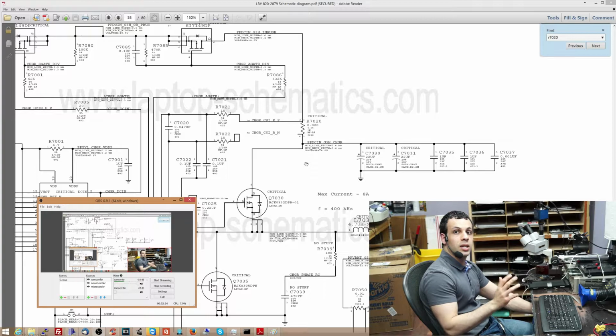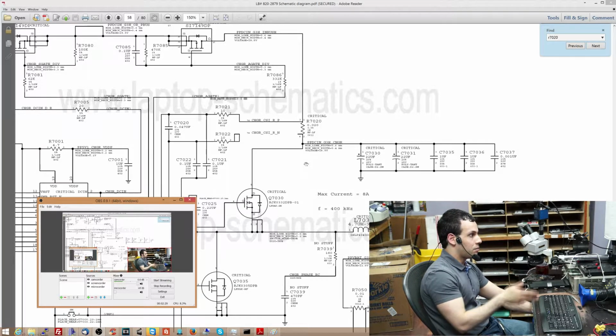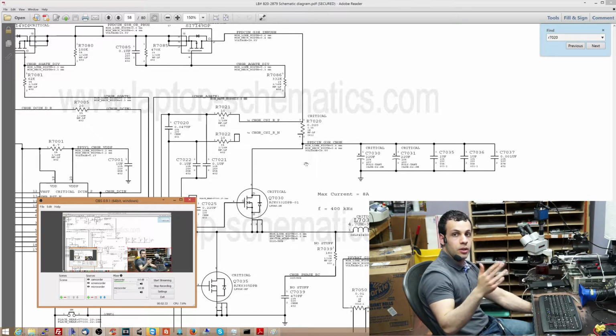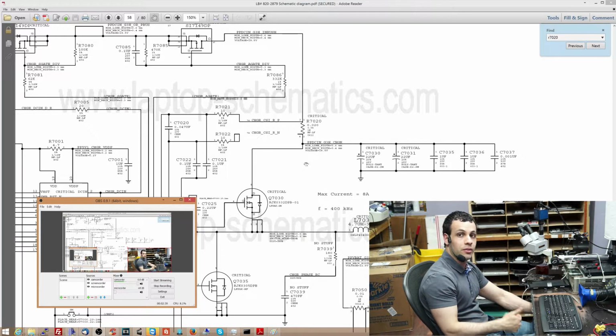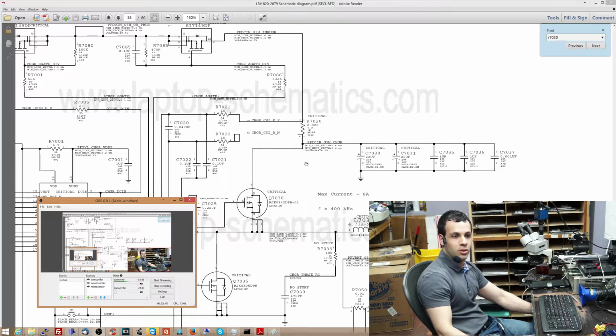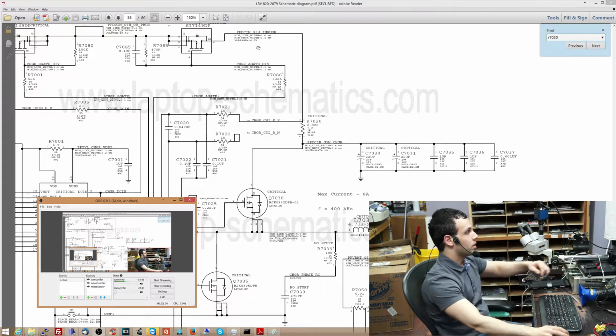Knowing this, we can then match different levels of voltage drop across that resistor with different amounts of amperage being used by the machine, and then we can tell the SMC to calculate how much battery power we have left, or how long it's going to take to charge the battery, or whether or not my charger is using too much power. Again, let's say it thinks my charger is trying to use 7 or 8 or 9 amps. It may turn the charging circuit off so the computer doesn't go on fire, and this is one of the things that this chip talks about to the SMC.